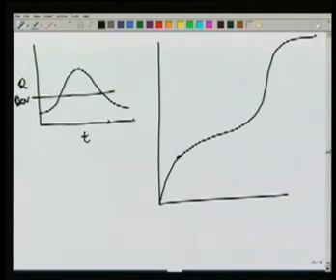So if you look at this figure of the runoff, during this time our supply is less than the demand, and therefore we must take water from the storage. During this period, water will be going from the stream to the storage after satisfying the demand, and again during this period up to t0, water will be taken from the storage to satisfy the demand.